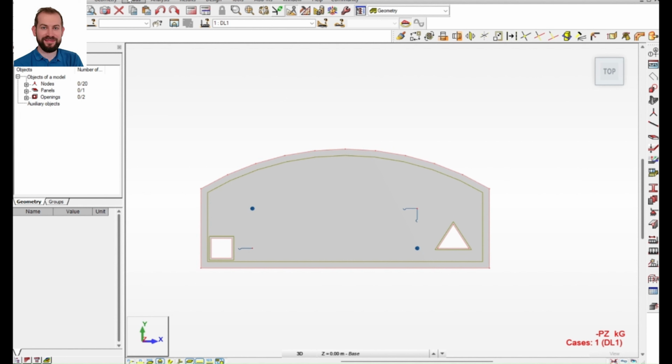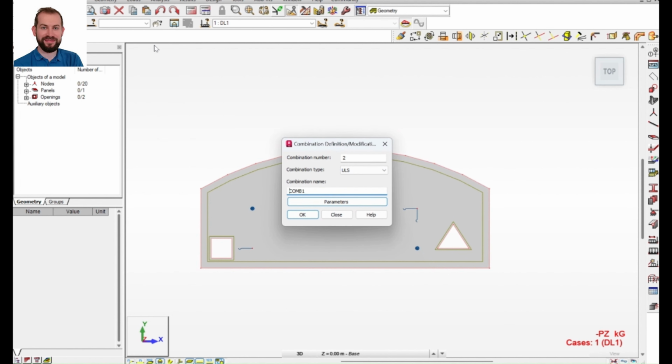So now we want to add some combinations. So from your calculations, you're going to have certain lifting coefficients added to the structure. So we want to multiply the self weight by, if we've got a lifting option 1, which is a tower crane, it's going to be a 1.2 factor.